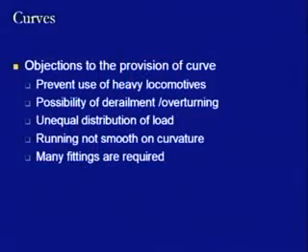Further, when we are talking about this curved section, what we have observed is that because of the centrifugal force, there is a tendency of the forward wheelbase to go in the outward direction, whereas because of the rigidity, the trailing wheelbase remains in the inward direction. So, in this case, we can see that there is a higher diameter coming on the outer wheel surfaces, whereas on the inner rails this diameter may be a little lesser.